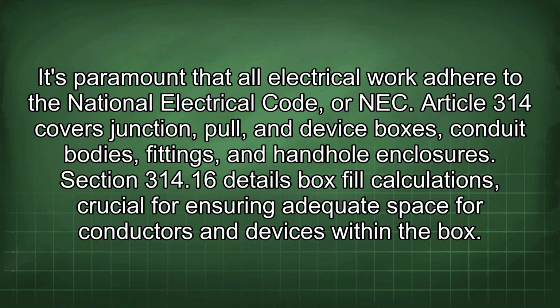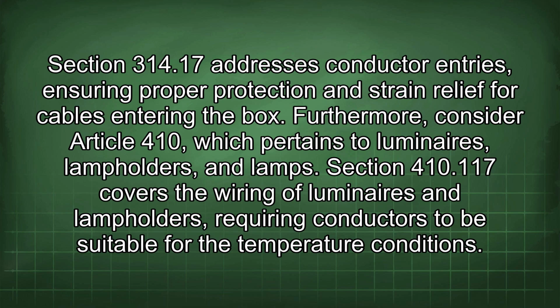Section 314.16 details box fill calculations, crucial for ensuring adequate space for conductors and devices within the box. Section 314.17 addresses conductor entries, ensuring proper protection and strain relief for cables entering the box. Furthermore, consider Article 410, which pertains to luminaires, lampholders, and lamps.